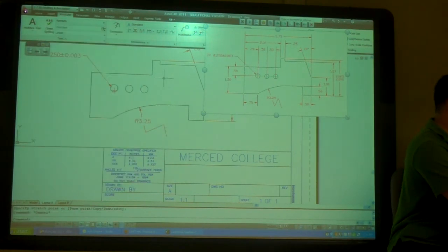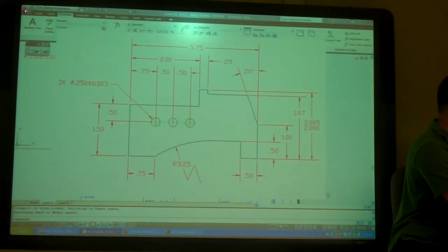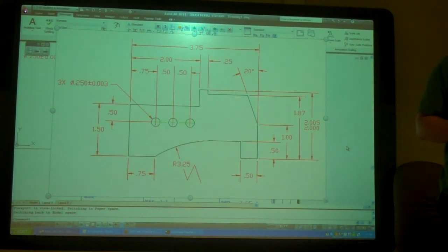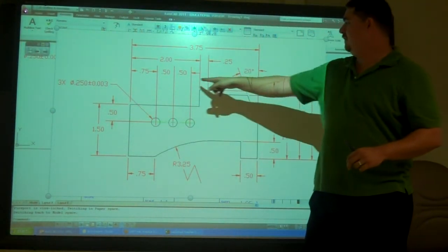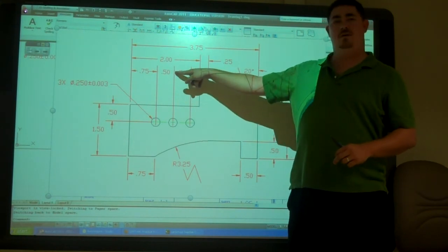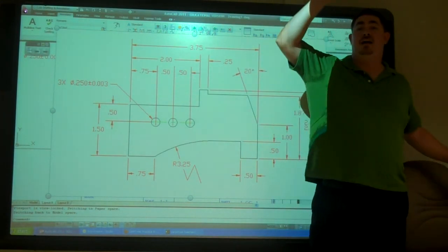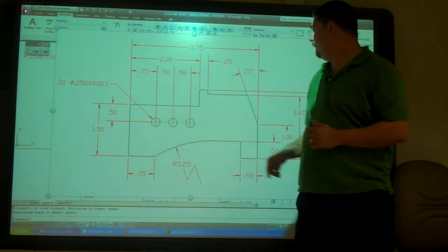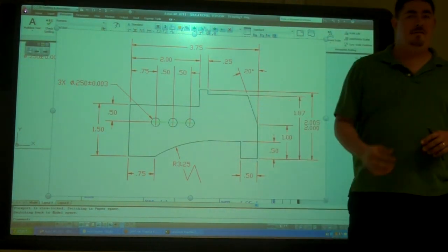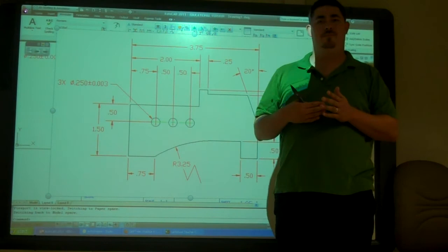Okay. Any questions on anything else on this practice 9? So we've done the tolerances, we did the jog, we did that. How do you turn this one off? You might want to turn the text off. So in dimension, go to dimension line, either 1 or 2, and turn it off in the properties. And so do this one. And then practice 10 is to go back through practices 1 through 8 and add dimensions to them.